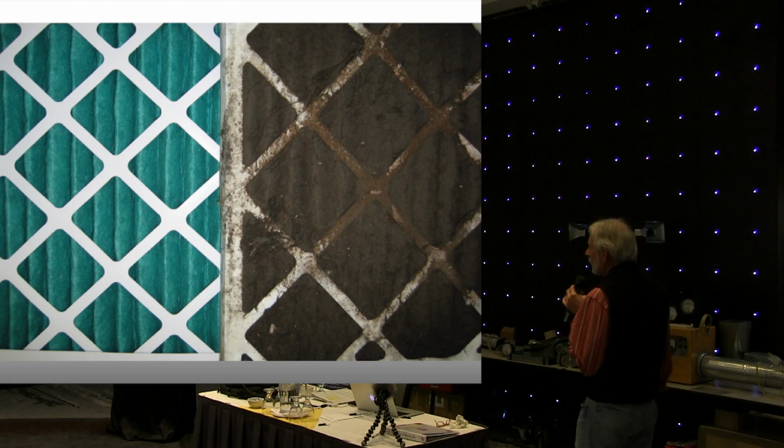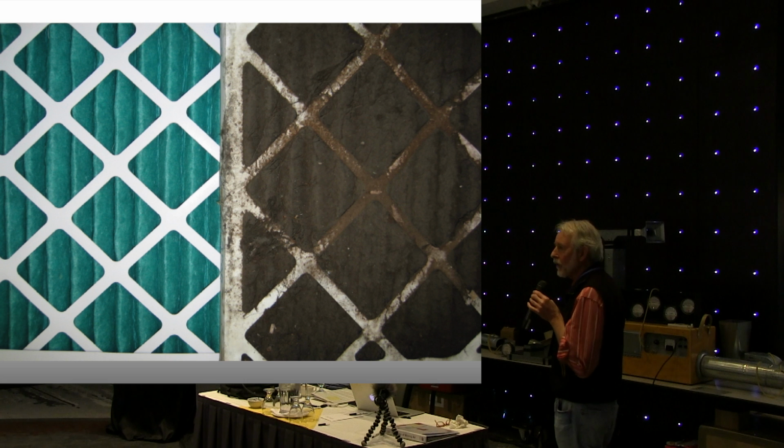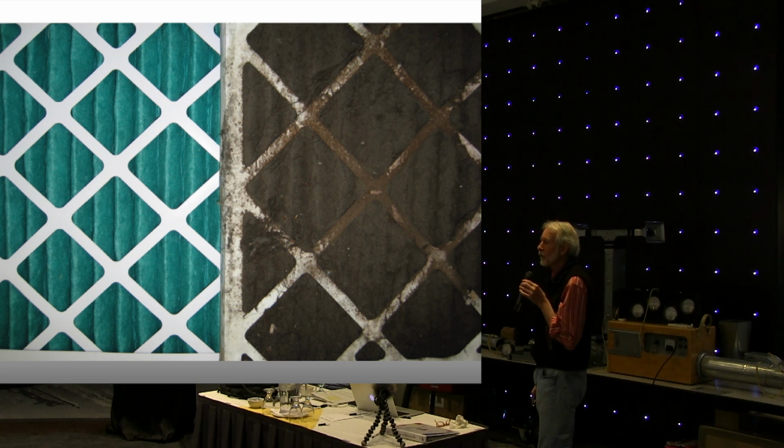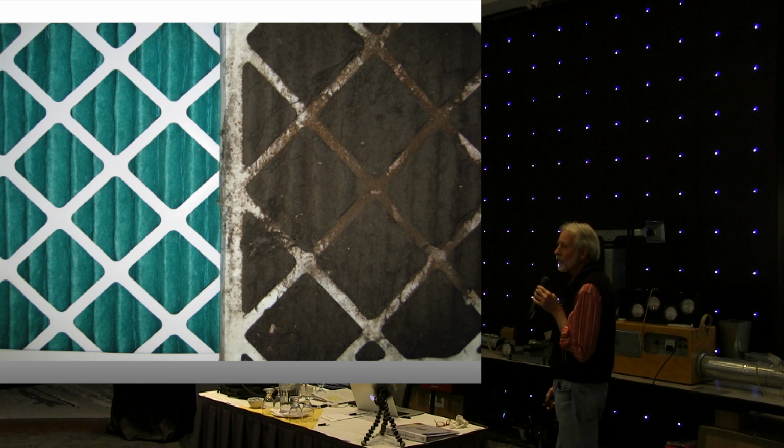This one here just looks absolutely gross. It's a 2-inch pleat filter, and the pleats are absolutely loaded to the full 2 inches depth, and it still flows air, because it was in a pre-filter configuration, and the particles are not small, they're big, so it filled up quite quickly. But it still flows air, and yet you think this was overdue for a change 5 years ago.